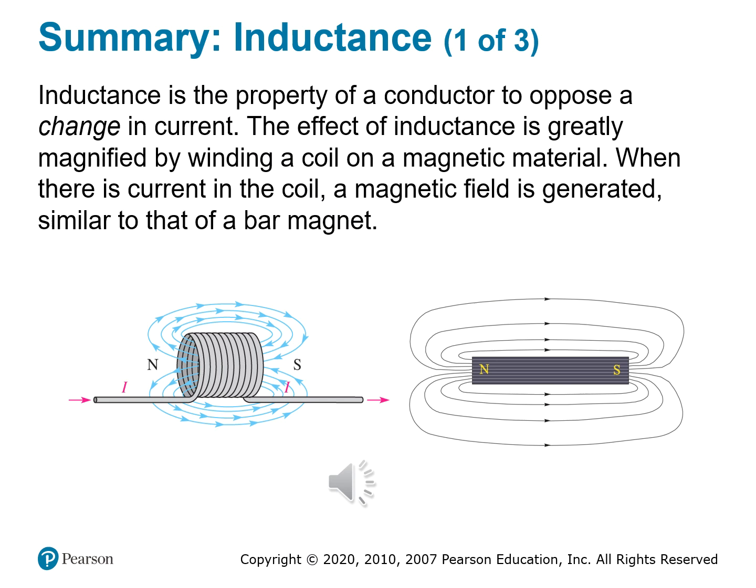And here are the key concepts to pull from this. When you try to increase the current, the coil builds a magnetic field. That changing field induces a voltage that opposes that increase. So when you try to decrease the current, that field collapses, again inducing a voltage, but this time it opposes that drop. So this behavior is a direct consequence of Lenz's law and Faraday's law of induction.